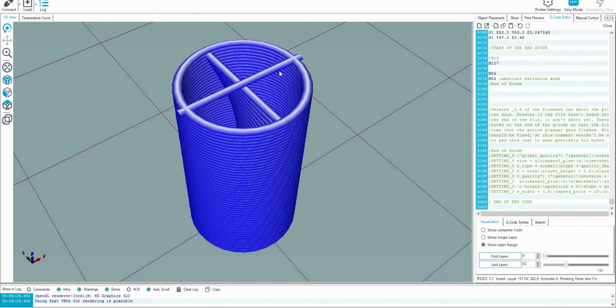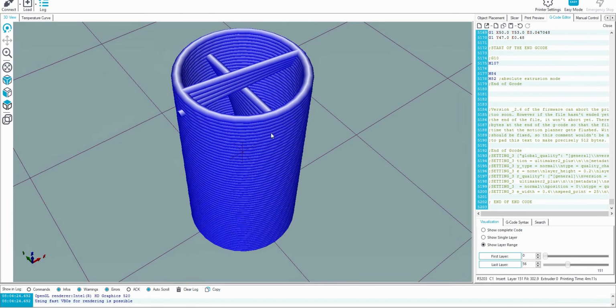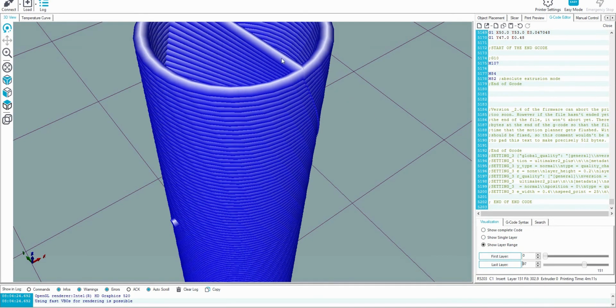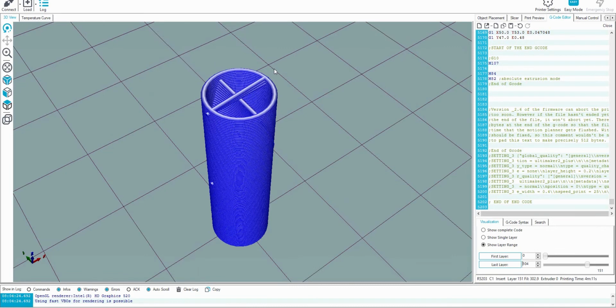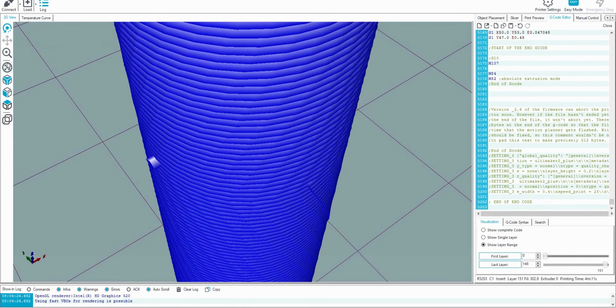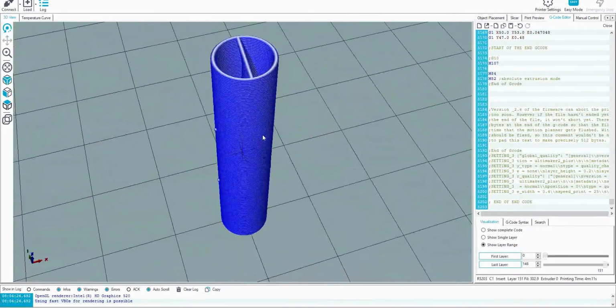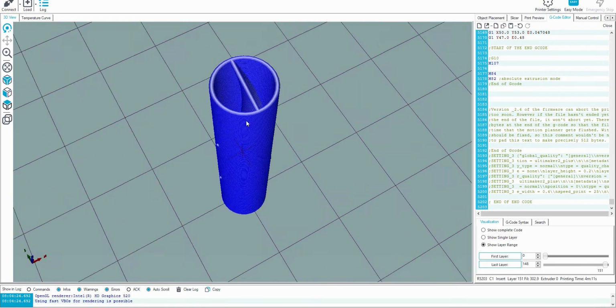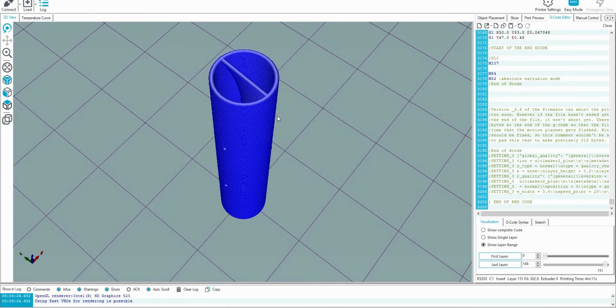So now this line has been expanded slightly, and similar for the next crossover point. This line is also being extended. And just those 2 lines have been varied. Nothing else has been changed. And we could of course change their speed or their extrusion rates or whatever we wanted. FullControl will allow us to change any segment in the whole structure in any way we want, as long as it can be controlled through G-code.